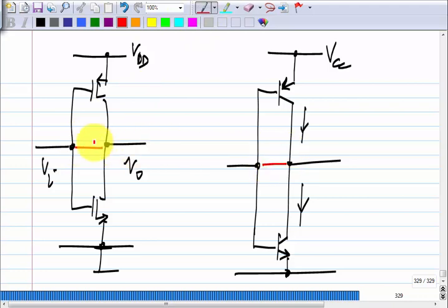So, in the self-biased CMOS, what was the dependence of this current on the supply voltage? So, it was VDD minus some sum of threshold voltages squared. What do you guess it will be here? No, why will it be square? It will be exponentially related to VCC. So, you just cannot use this. So, the current will be completely out of control. The same thing will happen here.